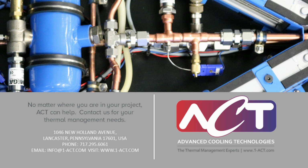One other place where it might make sense is if you can get away with, let's say, the conductivity of copper for a heatsink, but you just can't deal with the mass impact, embedding heat pipes into an aluminum body will have a comparable mass to just an aluminum heatsink, while having bulk effective conductivities well in excess of aluminum and generally higher than copper as well, if it's designed well. So I would say if you're interested in getting a cost point where it makes sense, you reach out to Dennis and his team, and they'll spin up some numbers for you.